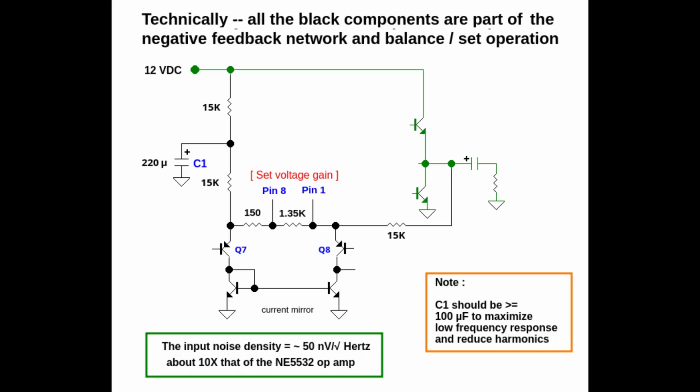For voltage gain management, if the junction between pins 1 and 8 is left open, the voltage gain is minimum, or 20. If you fully bypass the resistor between pins 1 and 8 with an audio capacitor, the voltage gain approaches 200. If you partially bypass the pin 1/8 junction with a resistor and capacitor in series, you can dial in a gain between 20 and 200. The datasheet covers this well, and I won't linger.